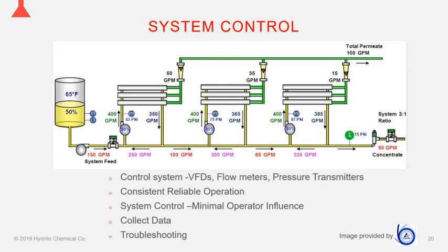Now, remember, they don't do that. The OEMs don't do that. It's another pump, more expensive energy. So they just design it so that they would see a little bit less efficiency on that one loop. So as you can see, we're going in at 400 gallons per minute. But as we've only permeated 35, our numbers look a little bit different coming out. We've got another 15 gallons coming down, so that's 365 joining our baseline. So we had 100 feeding into loop 2, and then we'll take 300 of that 365, feeding it into that recirculation pump to give us 400 gallons a minute.